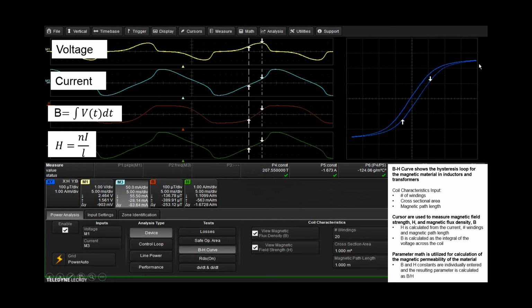But once we have that, we can plot this hysteresis. And this is interesting here because basically as you magnetize the material, once you reduce the magnetic field down to 0 again, there's still some residual magnetization of it, and so there's some work then to do to demagnetize it before you can flip it the other direction. And so this is going to give you that information.